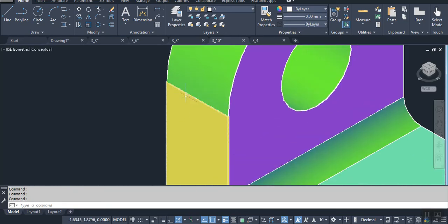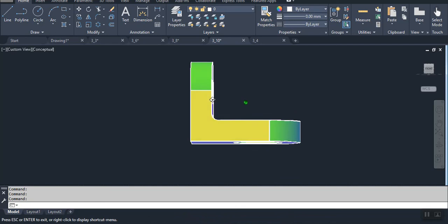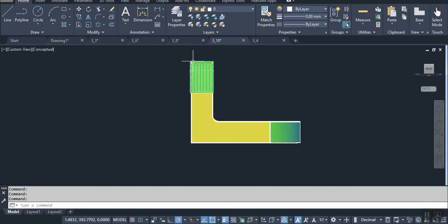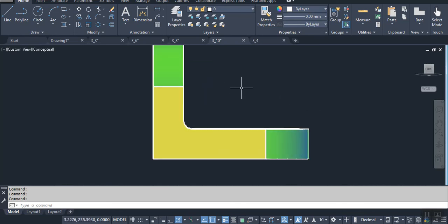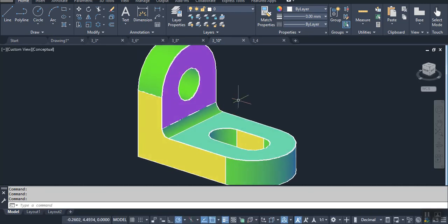If you were to look at this straight on, you might say, I'm going to draw the outline, and I'm going to draw a line here too, and here too, because I see a line there in AutoCAD. Well, AutoCAD represents that curve starting at that point of tangency, but you do not. In technical drawing, you don't draw the line.